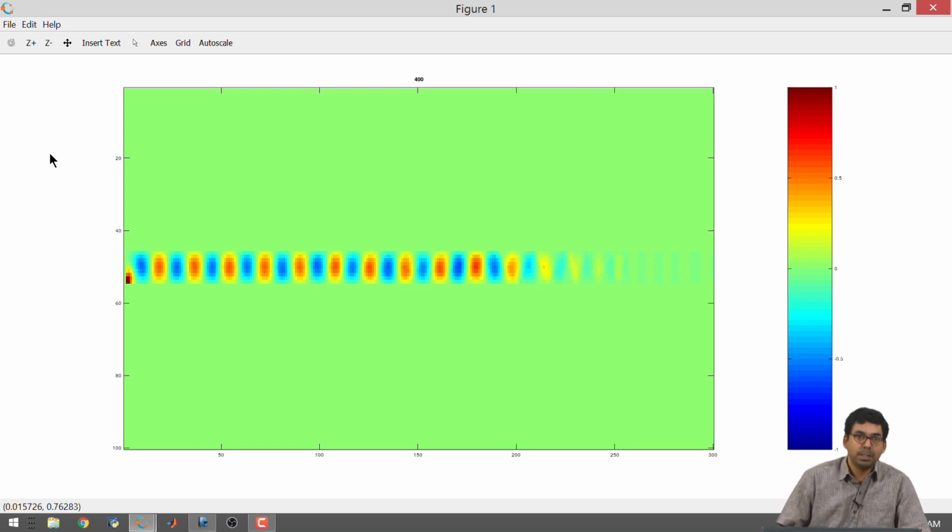So, we always have this question: what do multiple modes mean and how do I excite these modes? Usually a point source gives out light in all directions, so you could use a point source to excite all the modes, but if you want to exaggerate the presence of these modes, then you can move it in the cross section of the waveguide. But a truly single mode waveguide, no matter where you excite it, will eventually form a single mode pattern only. And in this case, it is just by adjusting the frequency that I was able to get this pattern.